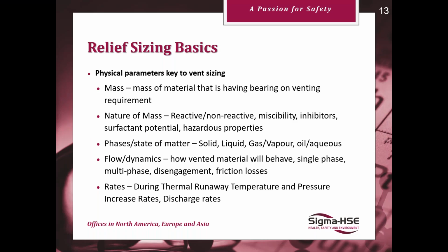And there are various physical parameters that are key to really ensuring that you can handle the amount of mass and energy that needs to be removed from that system. So even if the worst case does occur, using these relief sizing techniques, you can still maintain the integrity of your plant and not cause harm to your operators and such.